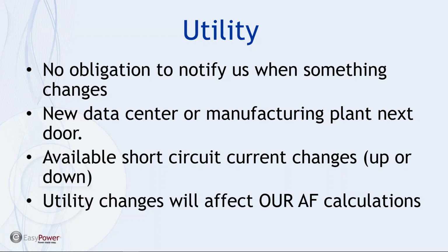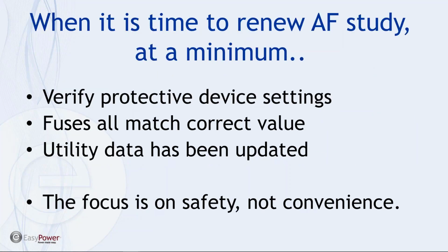And then if there are new transformers in the mix, it will affect our X over R ratios, and the ability to exchange energy will be different. Consequently, it will affect our arc flash calculations. So at the very minimum, when it's time to update your study, you want to verify your protective device settings.